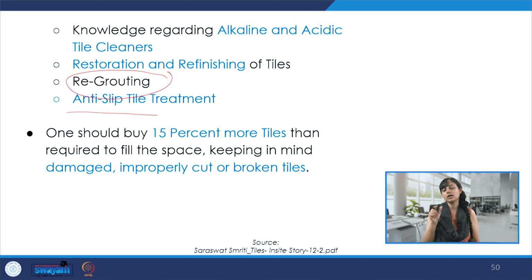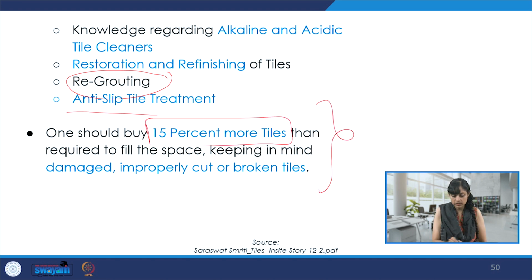Now, again, as a thumb rule, one should buy 15% more tiles than required to fill the space. Keeping in mind there may be some damage, some kind of a wrong cut, some tiles being broken, etc. So it's always good to have this sort of a thumb rule in place.